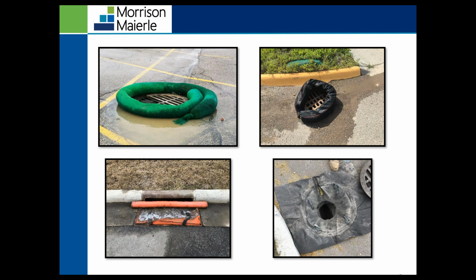So if you're not letting them be used for their intended use, you're going to create some ponding, or if stormwater is just going to go right around that inlet and go to the next inlet, it could get overwhelmed because it's not designed to handle that much volume of stormwater. So making sure that whatever you use for inlet protection, you're doing routine inspections to make sure no clogging or flooding occurs.